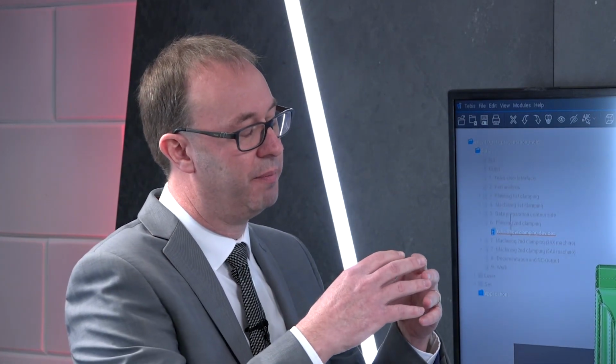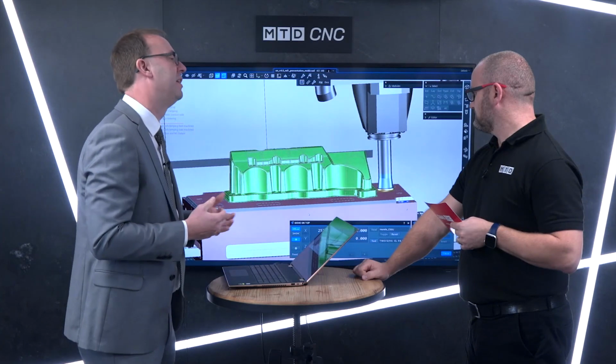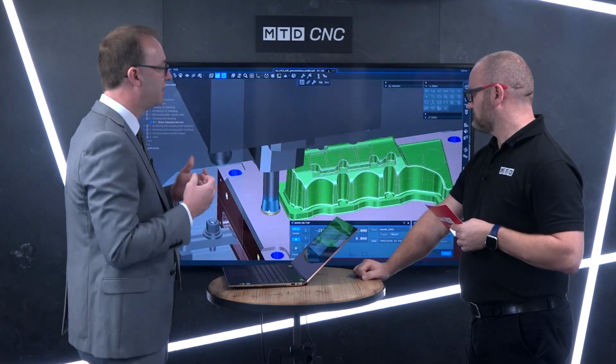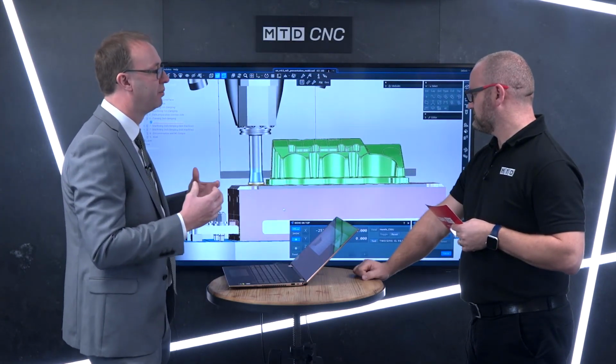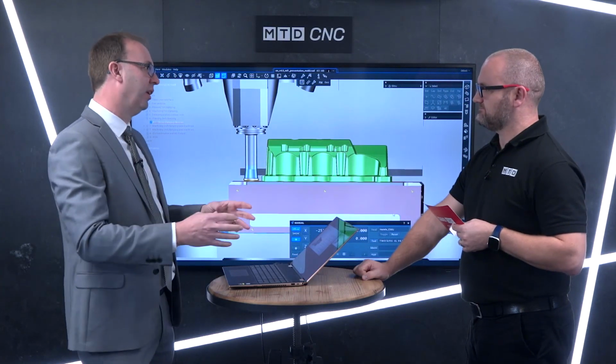Yeah, so what we do is we have 2 concepts here. First of all, we have a catalogue machine. And the catalogue machine is something that we would produce with a post-processor. And this will give you an idea of the kind of kinematics that the machine will produce. But what we actually promote is to have a full measured machine. Okay. Now this is something that what Tebis will do is we'll come in and measure your machines. We'll look at the controller, and we'll take the macros off the controller and embed them into Tebis.